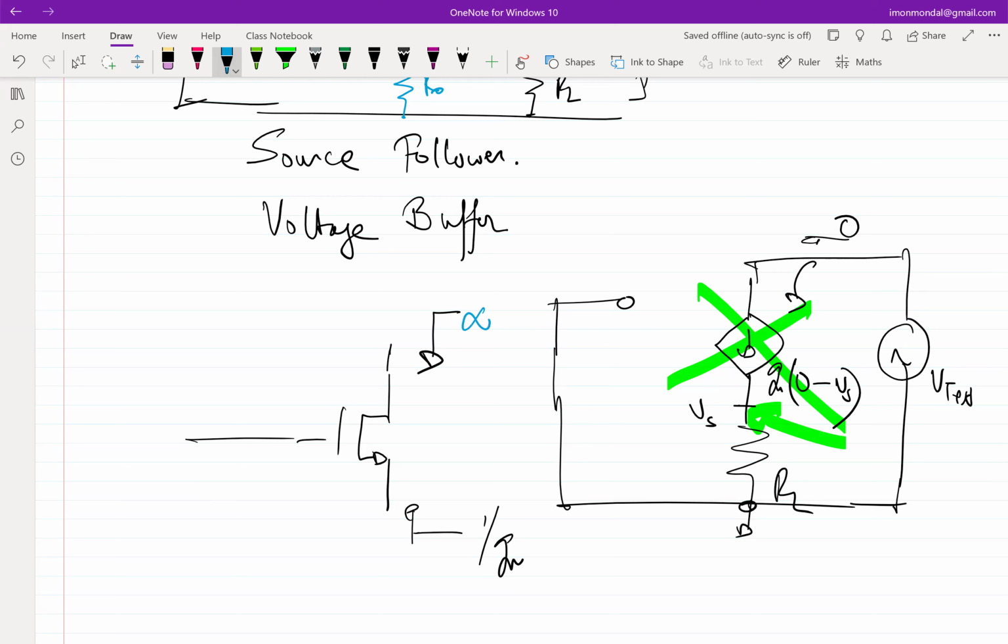Cool. So now, in a transistor, there are two places where I can apply inputs and two places where I can take the outputs, right? I can apply the input at the gate and I can apply the input at the source, because that affects the current. Similarly, I can take the output from the drain and I can take the output from the source, right?